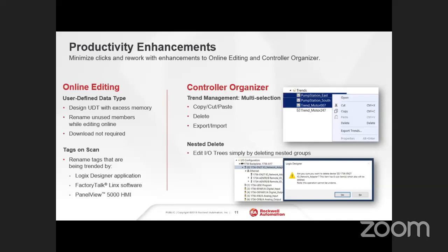So, for example, online editing, especially on UDTs and tags that are on scan. With UDTs, as long as you design your UDT with excess memory allocated towards it, then while you're online later, you can rename those unused members in your UDT that you've already allocated without a download required. And similarly, tags that are on scan, whether it's Logix Designer, FactoryTalk Linx, or your PanelView, you can rename the tags that are on scan.